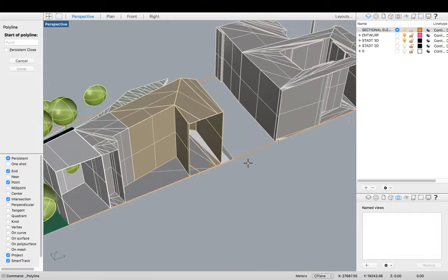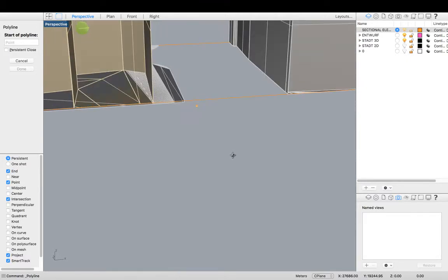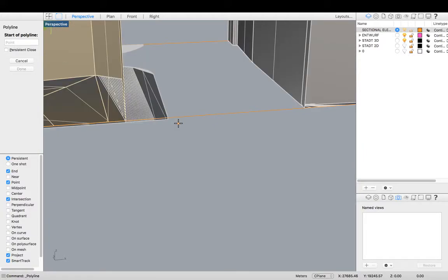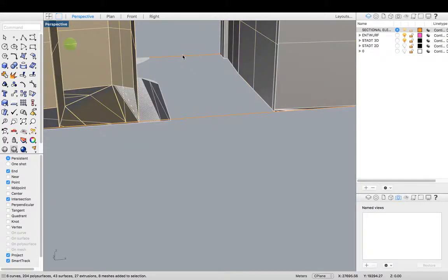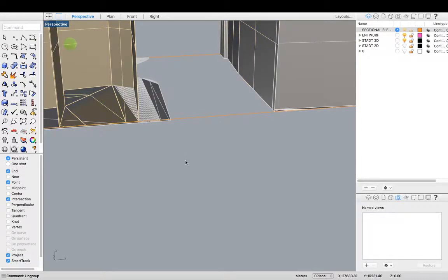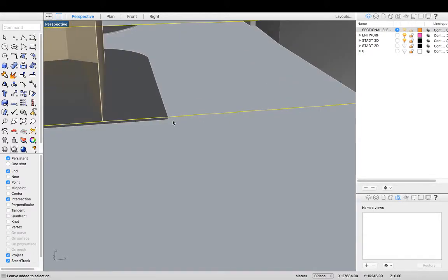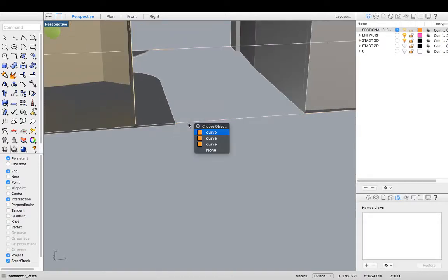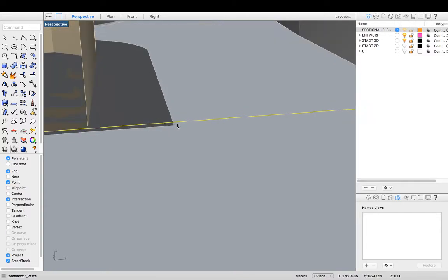Just to show you, we do actually need a floor for this model. To do that, you can simply duplicate, ungroup these objects. We can duplicate this boundary object by Command C, Command V. That should have duplicated, so now we have 2. And I'm going to move one of those boundary curves down to the floor level.